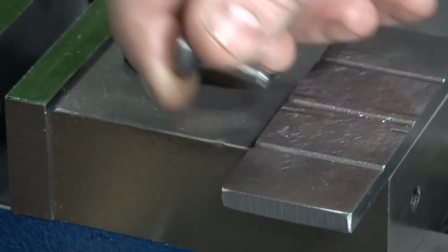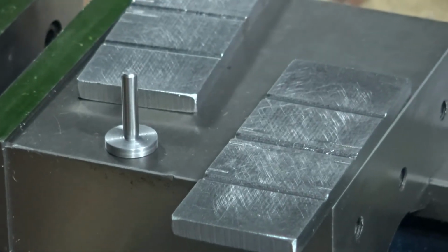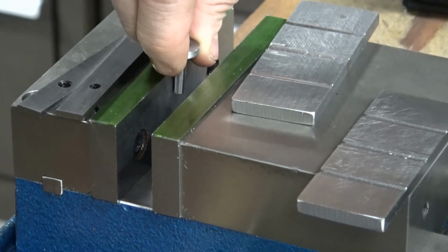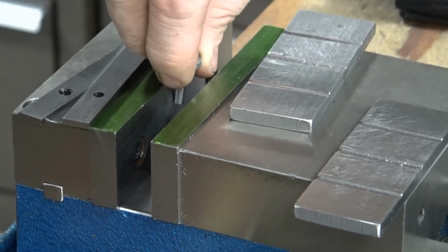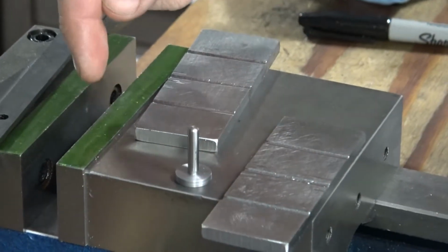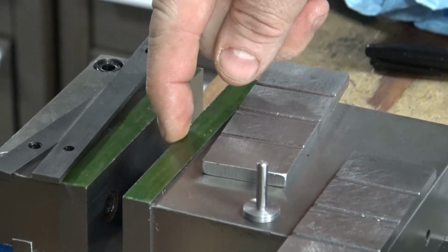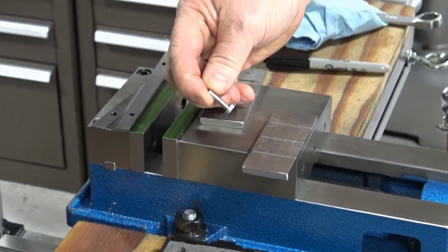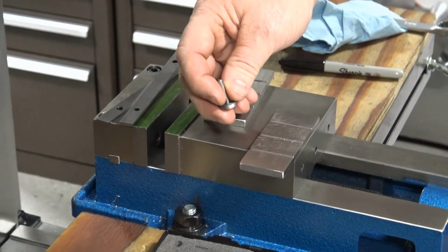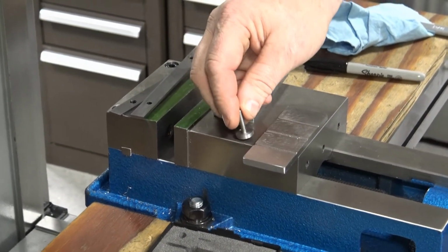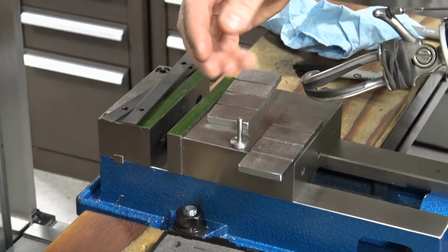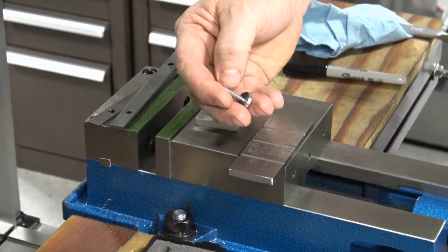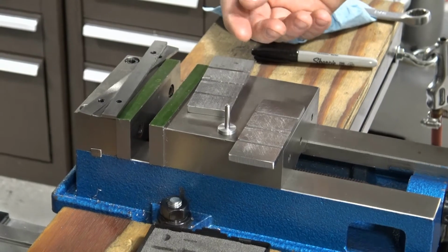Okay? The reason that I want to clamp on the radius is because if I were to just set it in the vise, I could definitely hold it that way, right? If I clamp the vise down, I could definitely hold it that way, but these are tool steel jaws. These tool steel jaws are heat treated, so they're actually harder than the hardness of the annealed tool steel shaft that we're going to clamp on. So what do you think would happen? You would likely compress it and put some little vise flats on the sides of that shaft. It's going to affect how good it runs.